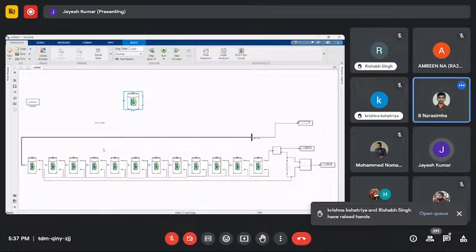So we have to connect this battery in string connections. Whenever you see a battery pack design, you can see nickel alloy strips connected to each battery. If each battery has 3.7 nominal voltage and 2000 milliampere-hour, that means a 2 ampere battery. So if I need up to 10 ampere, I have to connect the batteries in parallel connection. And in series connection, you add the voltages. I hope you are clear.